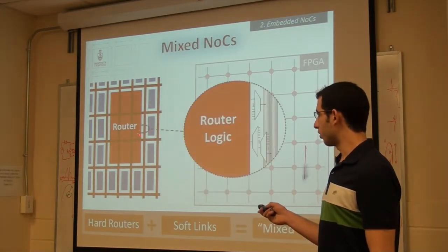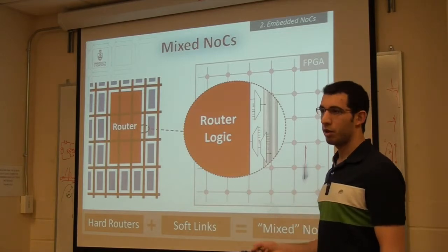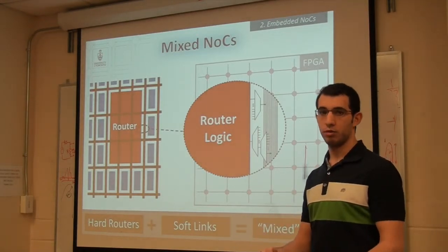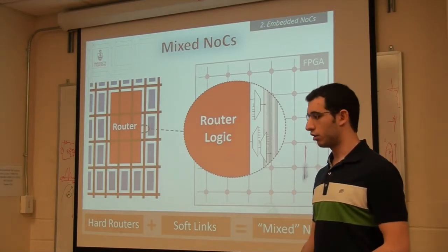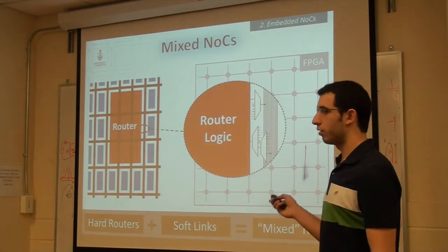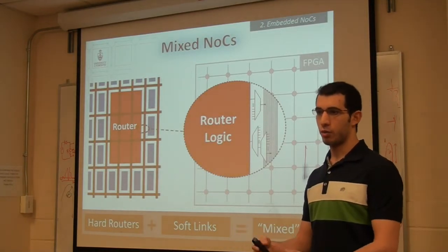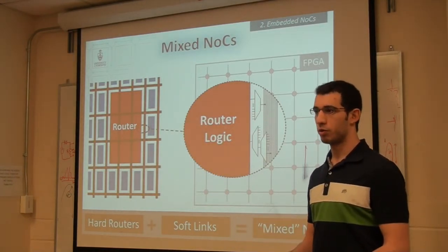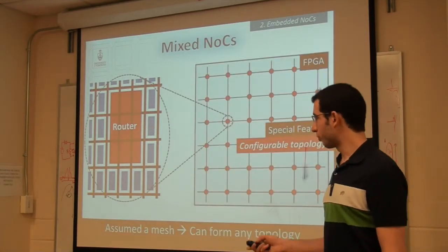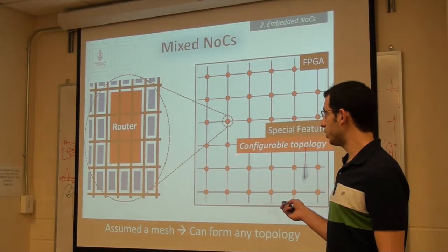So at the router interconnect interface here, we use the same kind of programmable multiplexing to access our network of programmable interconnect. That means 2 levels of muxing on each input and 1 level of muxing on each output. And we account for that area and power in most of our results as well. So of course we have many of those routers in our FPGA.